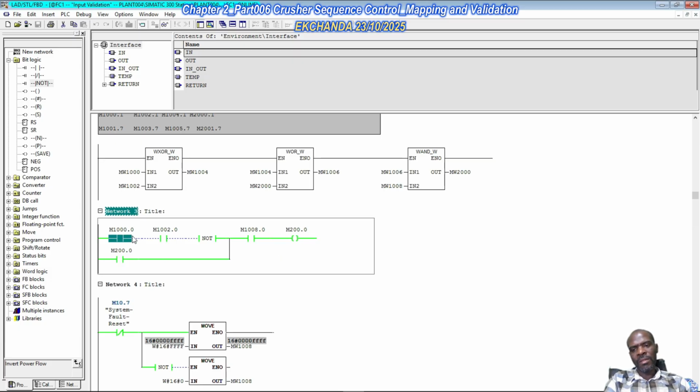Now the reason why I'm even showing you this is because sometimes, because of maybe a loose wire, you lose the connection to the PLC, and if it's a protection input, that will be flagged as a fault. So there'll be a situation whereby at some point you get this loose connection, the wire becomes loose, the system trips on account of a fault, and then you come in as a technician and check that